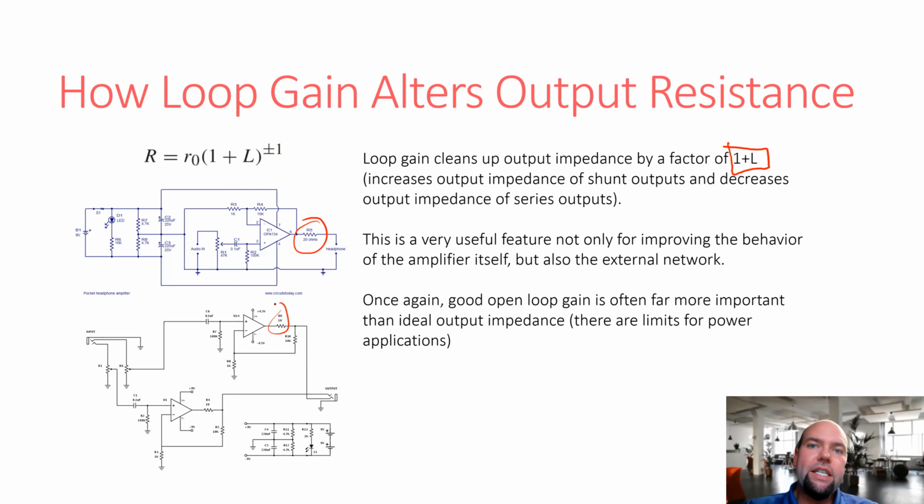Well, what's going on here is basically this resistor is designed to protect the op amp. Normally, if you're designing with an op amp, the op amp has a certain internal output resistance, and that output resistance offers some protection to the op amp against sort of blowing itself up. So basically, you want to limit the current that an op amp outputs. If you have too much output current, it's going to overheat and destroy itself. Some op amps have a certain amount of self-limiting current in the fact that they'll have some output resistance, but a lot of times it's not enough.